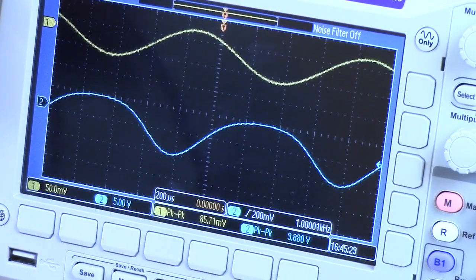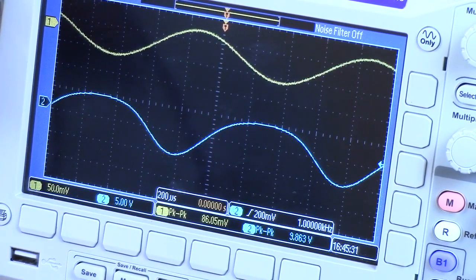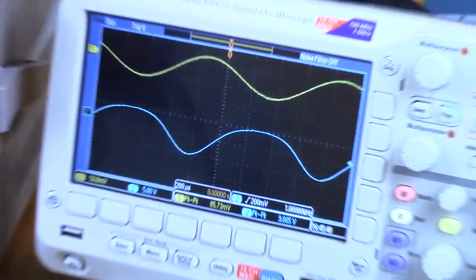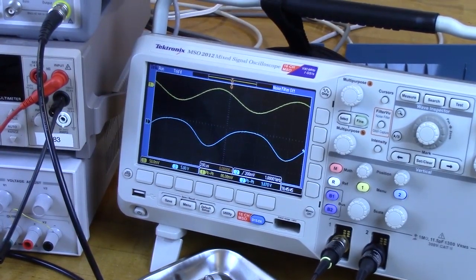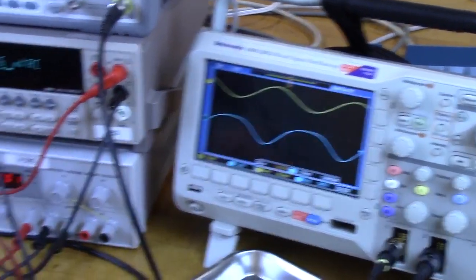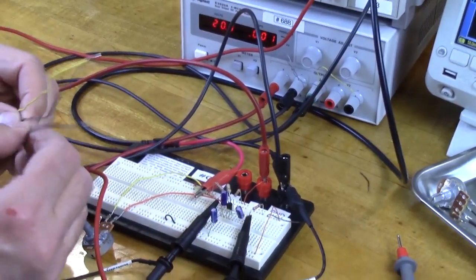And again, I'd like to do them both. Input impedance with and without CE, output impedance with and without CE. So what we're going to do for that is, we're expecting an input impedance of about 20 or 30K. And so for that, I got us a 100K pot, which should give us plenty of range.